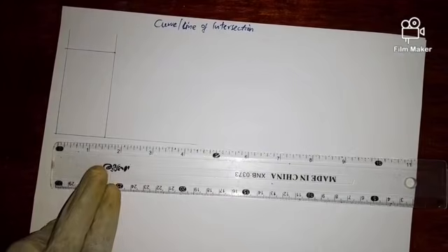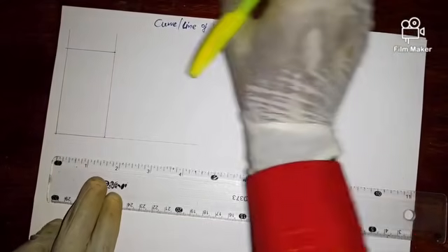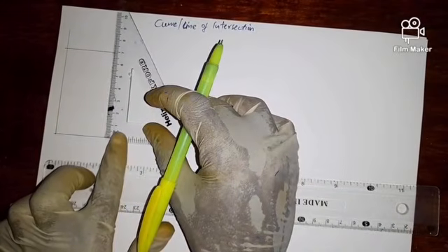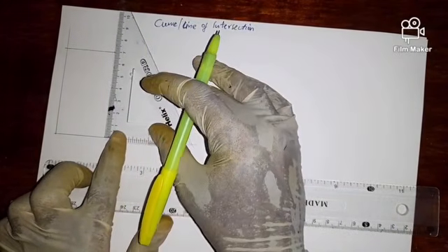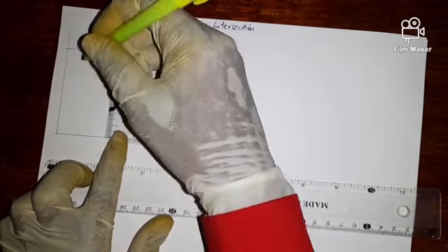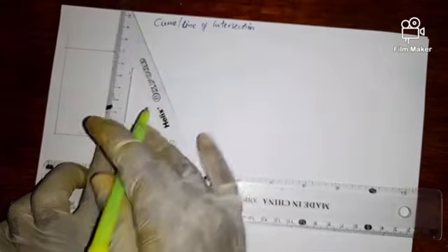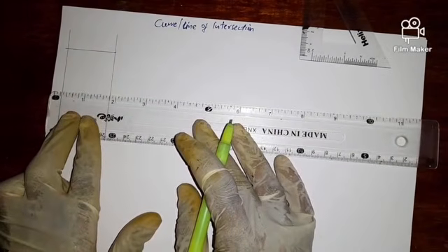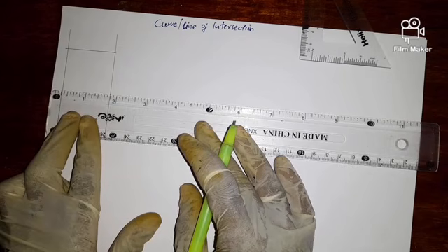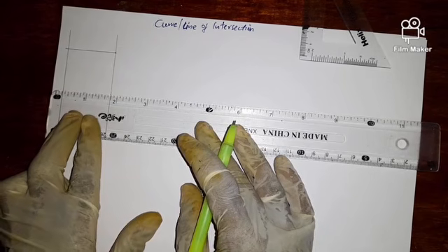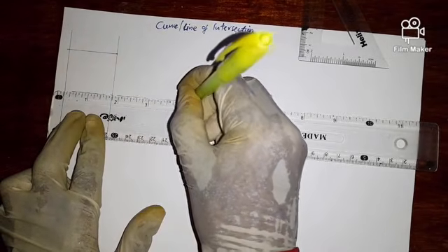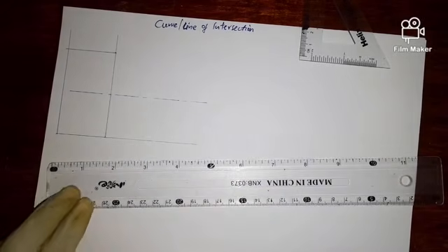We can include the horizontal cylinder that joins it at 5 mm above the base. So we are going to measure that 5 from the base, and we get that point where the center line for that cylinder passes through. Here it is. Now we can draw the center line. This is our center line.